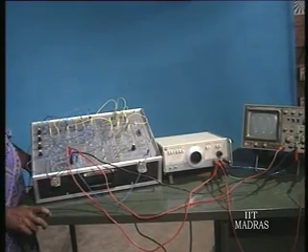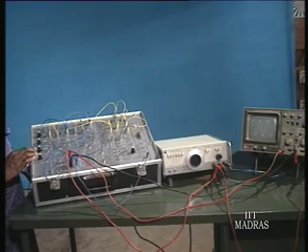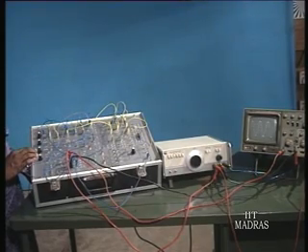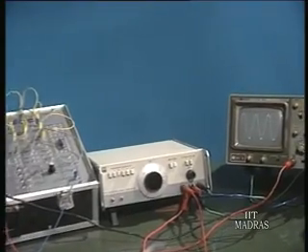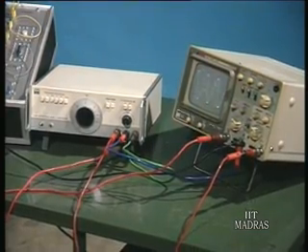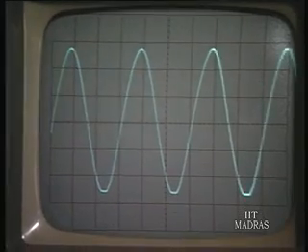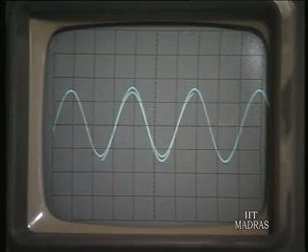She has assembled the same circuit now, and it is oscillating there. You can see the screen. Now, please change the feedback so that it stops oscillating. It stops oscillating because she has introduced more negative feedback than positive feedback. Now, introduce positive feedback, so it starts oscillating.